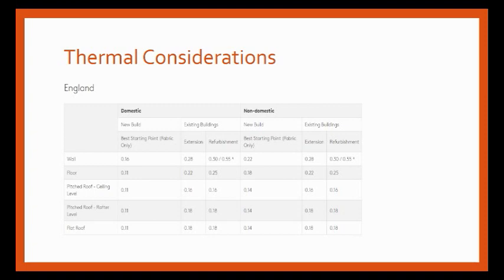Moving on to thermal considerations, there was no U-value requirement mentioned in the brief, and as one of our company values is sustainability, our choice of cladding will be high in thermal retention to reduce the amount of energy consumption that may otherwise be necessary to power heating appliances. According to Kingspan, for non-domestic buildings, the U-value must meet 0.22.